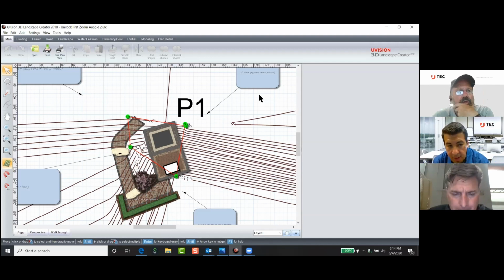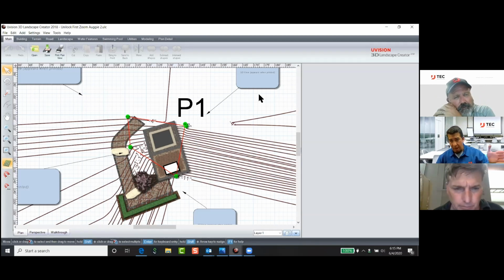Yeah, one of the things too, Brian, on the lengths. So Patty talked about the height. When we were doing the initial distance measuring, we did test the distance and how accurate that was. We took a 25-foot span, and we did measurements at 5 feet, 10 feet, 15, 20, and 25. And when we got all the way to that 25-foot mark, we had a 1/4 inch deviation on that length, which over a 25-foot length is very acceptable. That's within the tolerance of that span of distance.